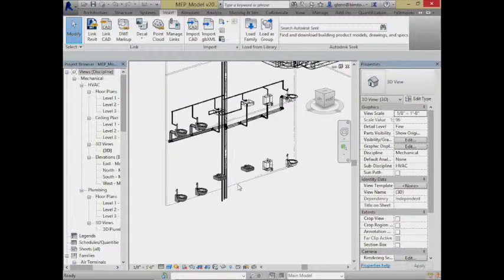Ultimately, this line is going to come running along. We're going to need to get from these individual units, carry this waste through the lateral to the sewer, and that'll typically happen where all the laterals on different floors join together. We'll have some vertical pipe that this all gets teed into. It looks very squishy only because I ran out of whiteboard space. It has to be bigger still. I'll call this a riser. So that's a riser. This guy over here I'll usually call a lateral. And that's how the waste system gets carried away.